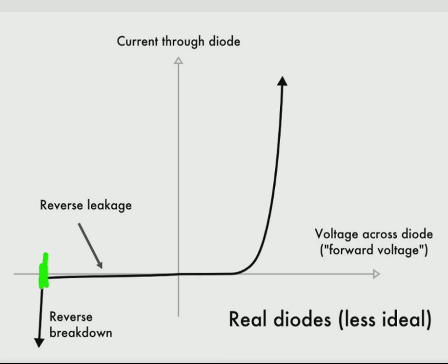It helps to provide a stable voltage reference in a variety of circuits, such as a reference for an amplifier, and the Zener diode is also used in a stabilized power supply. So even if you have variation in the load, your Zener diode will maintain this voltage across it, and it will provide a constant stabilized voltage to the load.